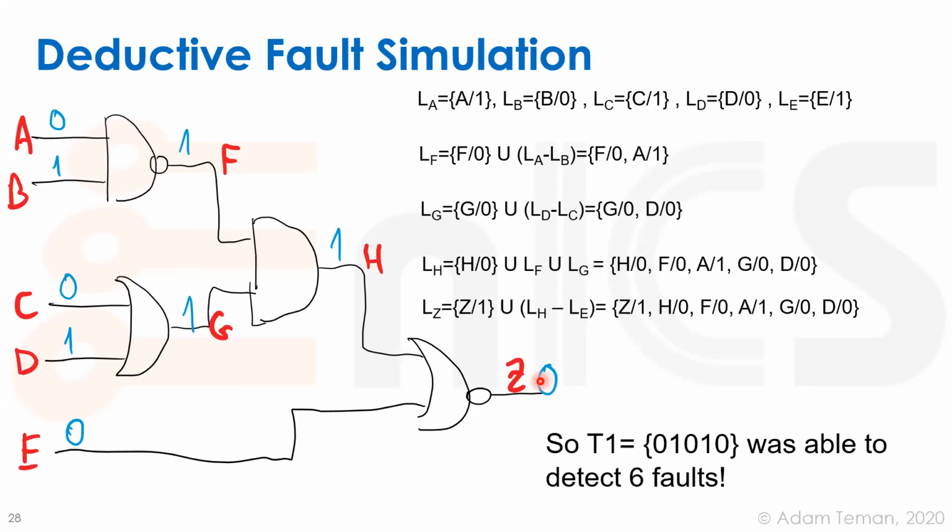So just to add to what Udi's saying here, right now our goal is to save test time, by providing the minimum set of vectors that will cover as many failures as possible. If we want to do some debug, which is not usually done, and is for sure not done in production when we have good yield, where we just throw out the few chips that are bad, then we could look for the exact vector that's going to show this failure and not show another failure, or give this vector and another vector which will differentiate, so that we only have this failure.